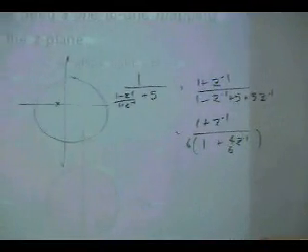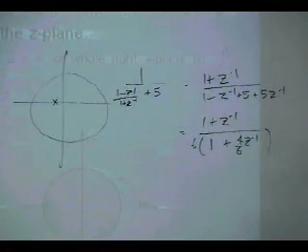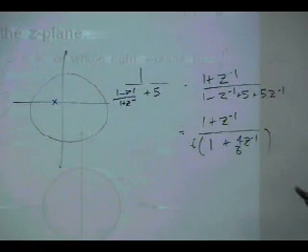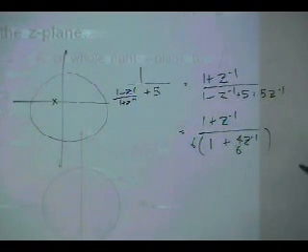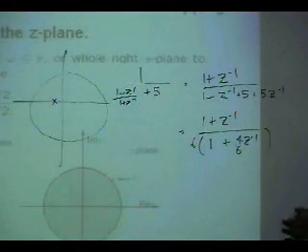So they don't care where the pole is as long as it is inside? Yes, we don't care where the pole is as long as it is inside the unit circle, at least for the stability. And the transformation will make sure that the pole is correctly placed to meet the specifications. So it still gives you an H of exponential j omega which meets the specifications. So this is the job of the transformation. The transformation is ensuring that the pole is inside the unit circle, guaranteed.